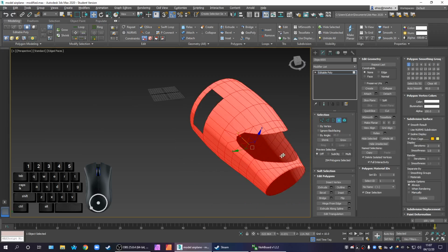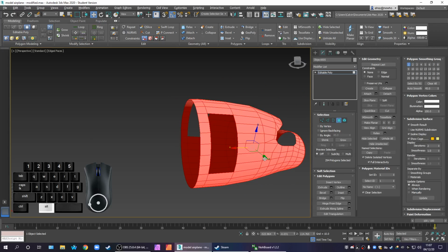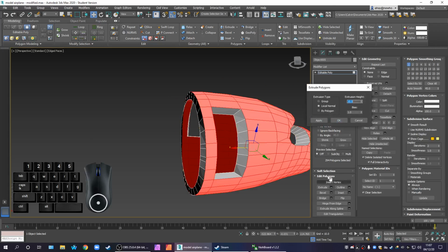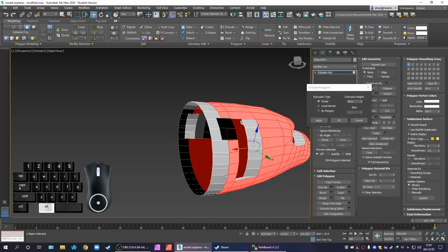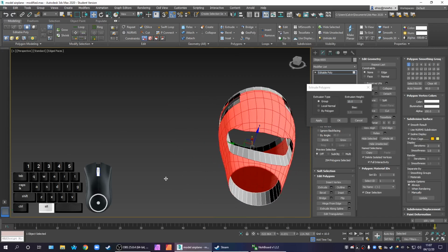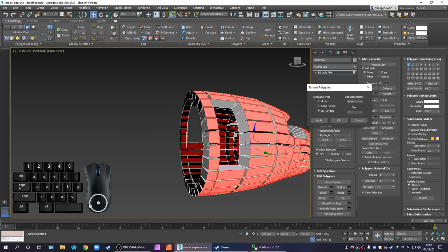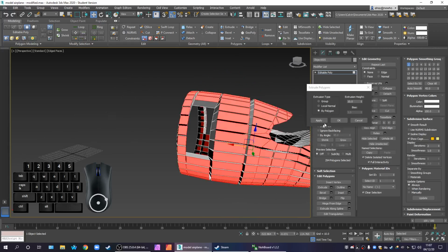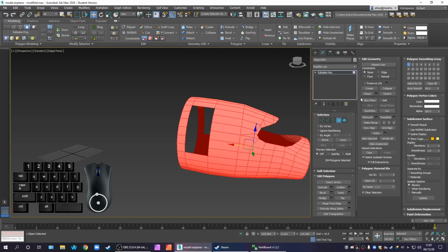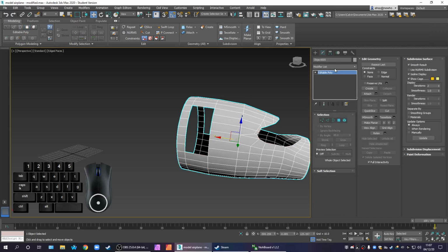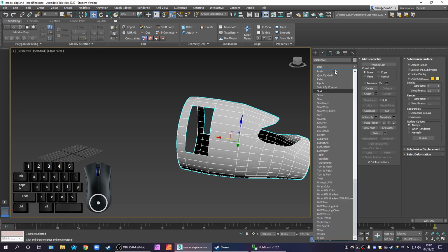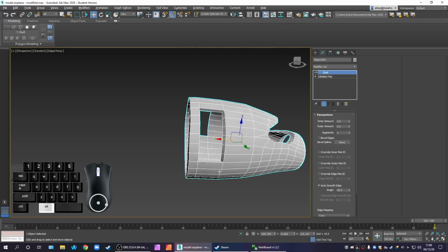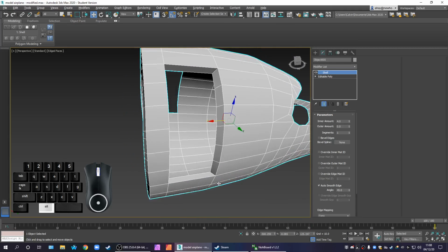And in the canopy, the local normal trick is actually working really well for us. The other thing we can do is extrude by group, but that's a total disaster. You can extrude by polygon. So local normal is what you have to do, which is what the shell does by default. So we're going to shell.